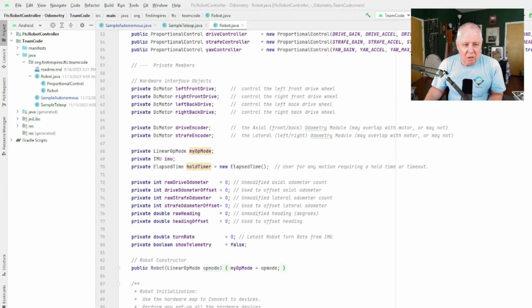If you were also using the motor ports to actually run motors, I would recommend that you just create 2 more motor classes and just use them to send commands to the motors. Basically have an encoder variable and a motor variable and use them separately, as long as you don't issue conflicting commands, like change the mode of one and expect the mode of the other one not to change.